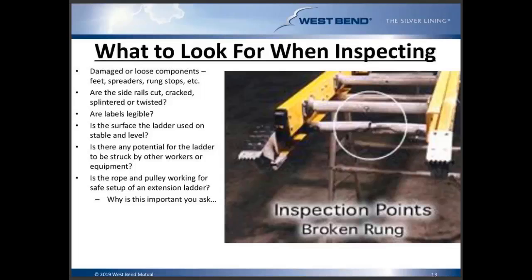Are the side rails cut, cracked? Looking for any splintering, twisting, any type of holes that might have been drilled in them, or welding slag. All of those things can deteriorate the structural integrity of those side rails, and again might be a situation where we'd want to get rid of it.